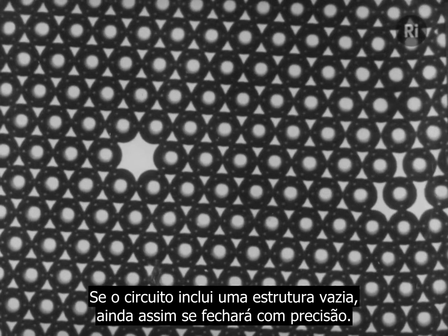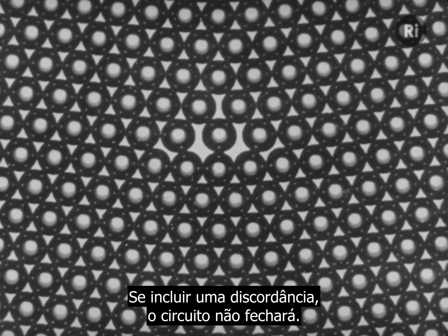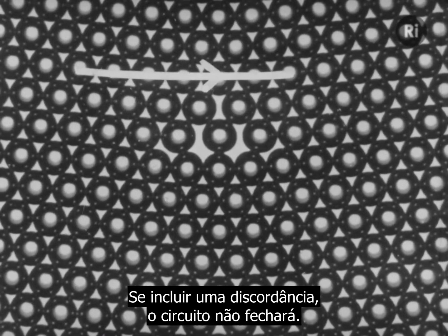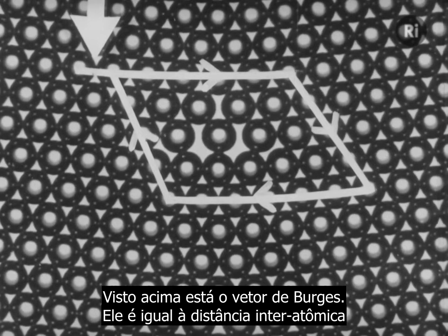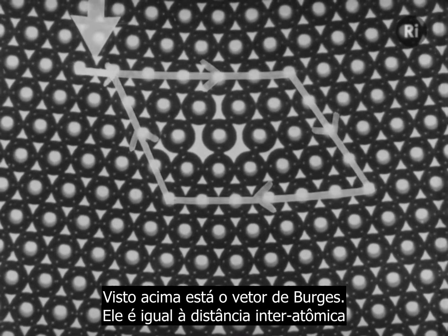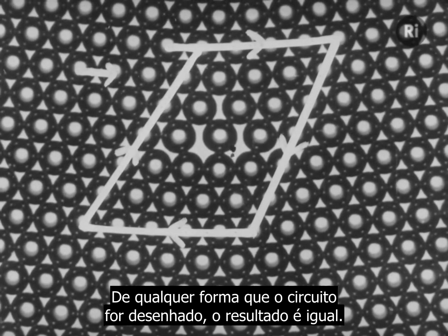If the circuit includes a vacant lattice site, it will still close exactly. If it includes a dislocation, it does not close. The residue is the Burgers vector. It's equal to an interatomic distance. However the circuit is drawn, the result is the same.